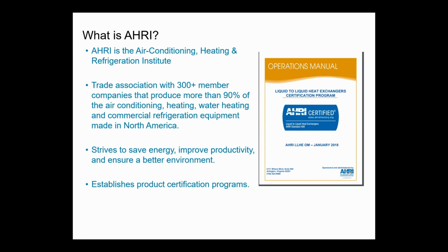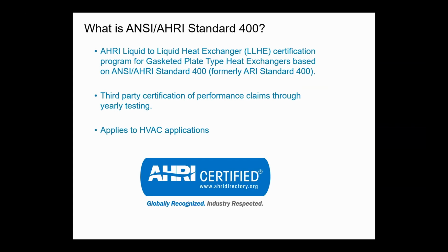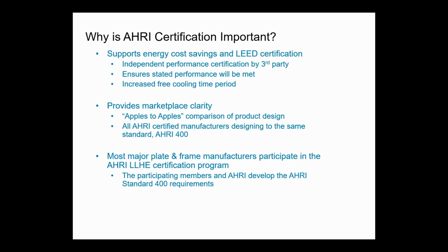If anyone right now is already reviewing specs or has any familiarity with AHRI, it's very well adopted across the industry. Now AHRI has a standard, standard 400, where, for instance, if you're in a selection software and a company is a participating member, you're going to see the option to select AHRI 400. AHRI 400 is essentially saying that that heat exchanger was tested in accordance with AHRI 400, which means that every year a sample of all different versions of those heat exchangers from whatever participating manufacturer you have is pulled, tested by a third party, and verified. So it's just trying to make apples to apples in the industry, make everything comparable.